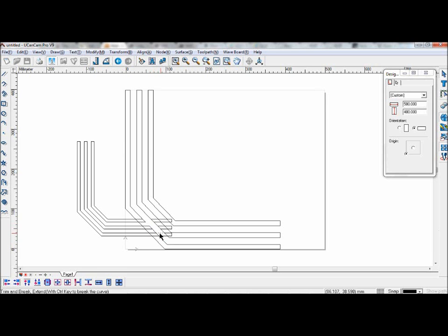To connect the lines again, hover your mouse over where the line should be. When you see the mouse is like this with the dotted lines, left click and they will connect. To separate the lines or break them, hold Control when hovering a mouse over them.